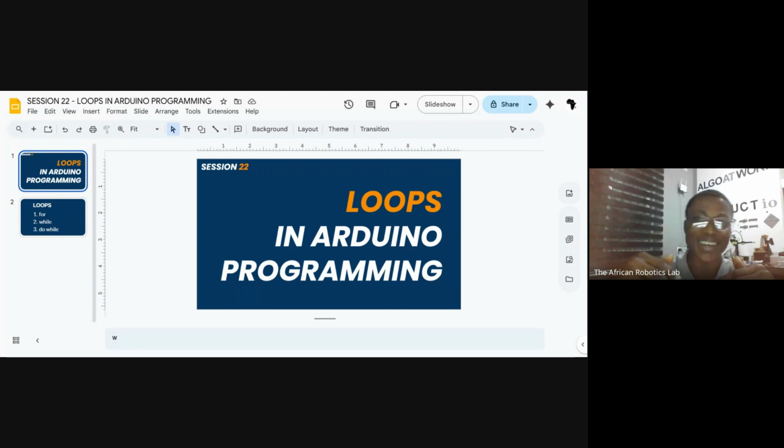And so for the I2C communication protocol, there's also just two pins: serial data for data, and then serial clock for timing. And then lastly, we took a look at SPI, serial peripheral interface. For that one, it's not just two pins; it's 4 pins.